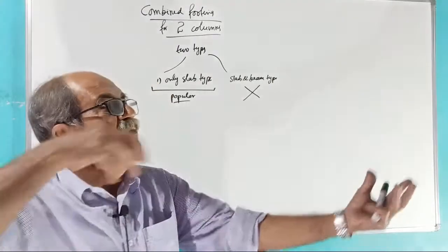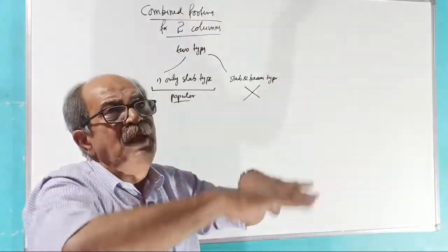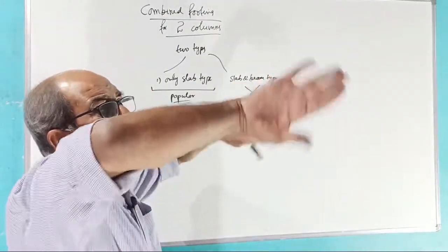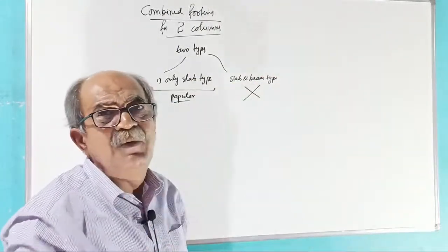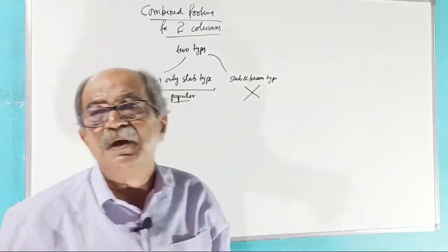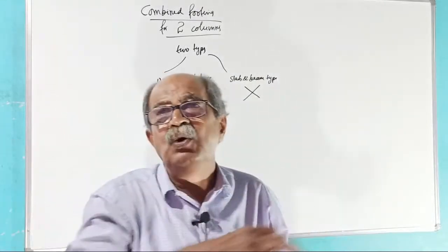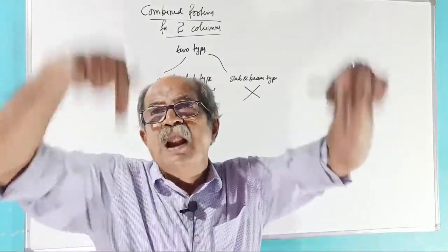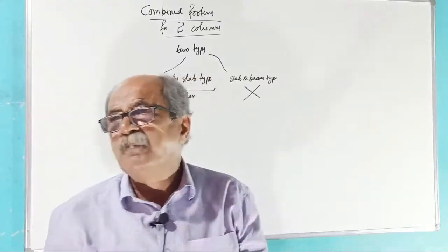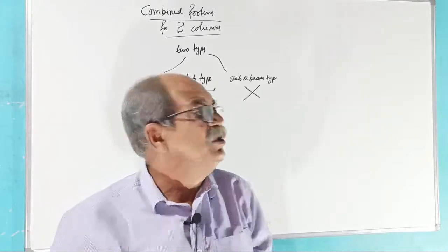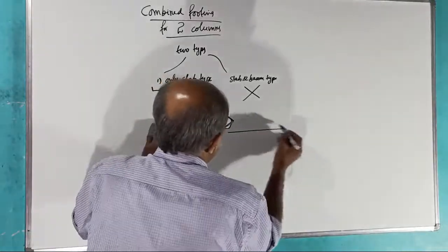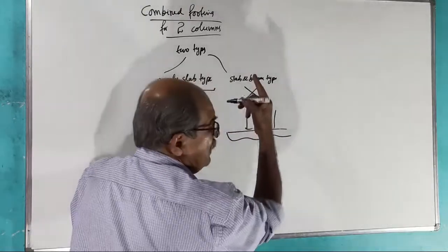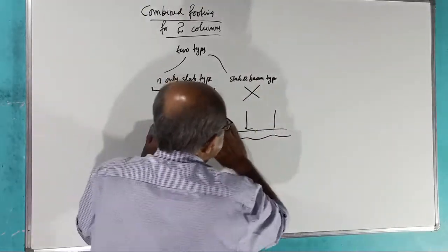There, the column will rest on the beam, and the slab is below. I will tell that the slab is bending as a one-way slab, as a cantilever, fixed at the face of the beam. The beam is subjected to longitudinal bending. See, this way, like two columns here and upward load transferred from the slab. It will be like this almost. Beam design will be like this. See, then same except the BMD. Okay, therefore this I will tell.